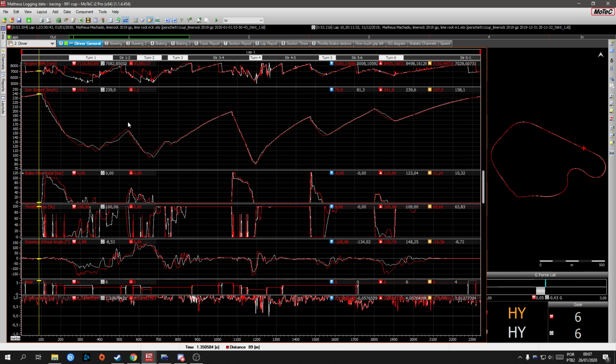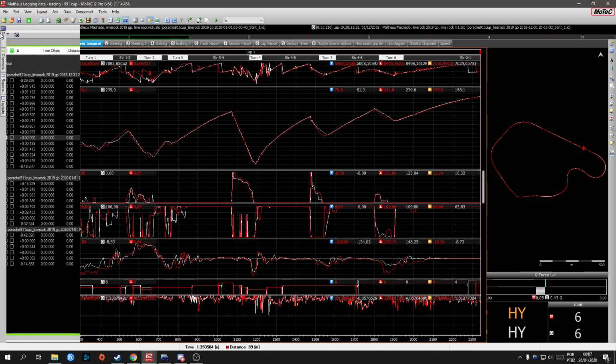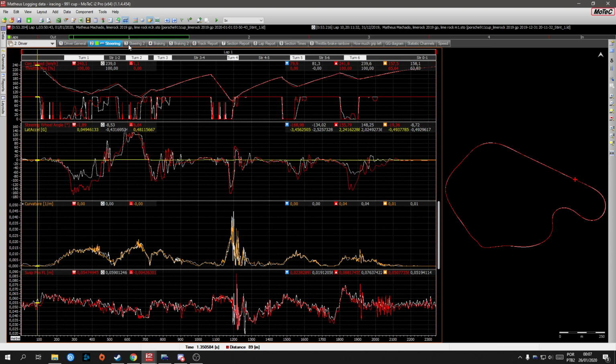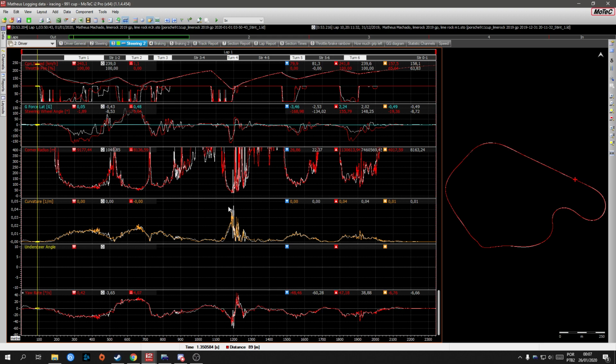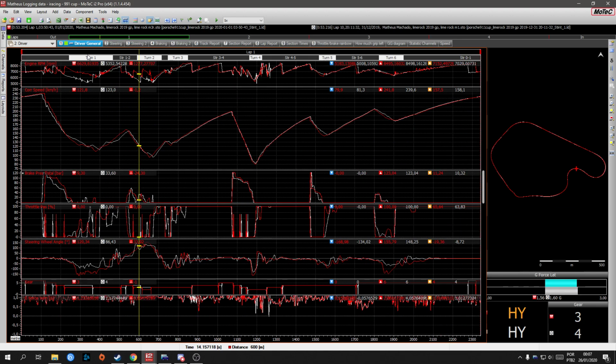And if you compare those two laps, you can see that it's very oversteery in the data where the car didn't have any rear downforce, especially at the braking zones. So the car doesn't generate much downforce, so that's why you don't see a huge difference. But look at the steering wheel angle of the white lines. Look at how I can use much less steering wheel angle, and it vibrates a lot.